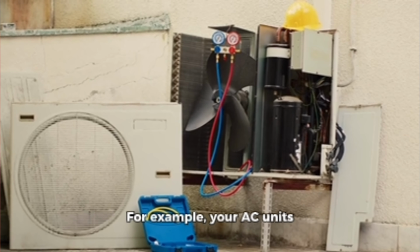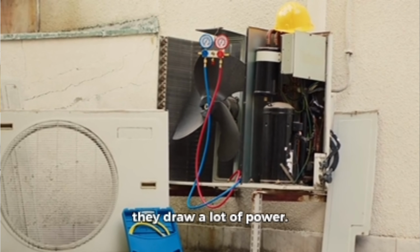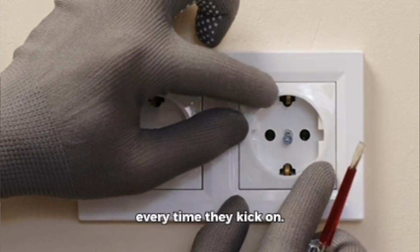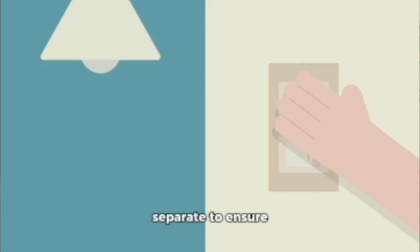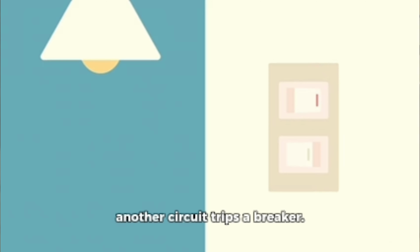For example, your AC units will need their own dedicated circuits because they draw a lot of power. You don't want them causing a power outage every time they kick on. Similarly, your lighting circuits should be separate to ensure consistent illumination, even if an appliance on another circuit trips a breaker.